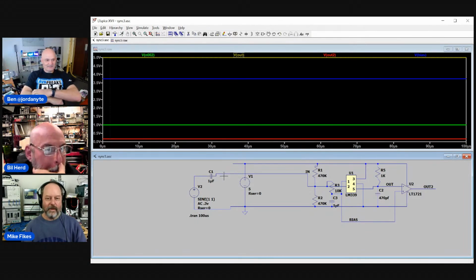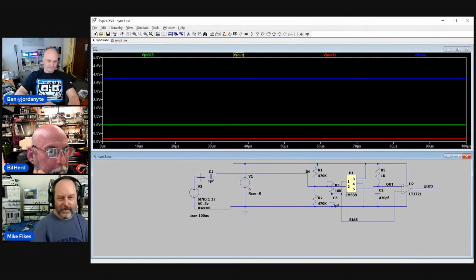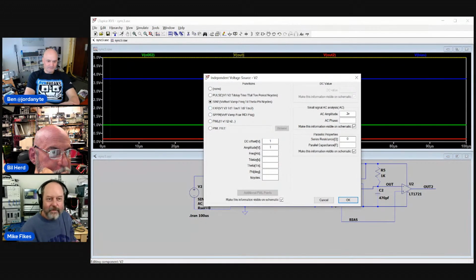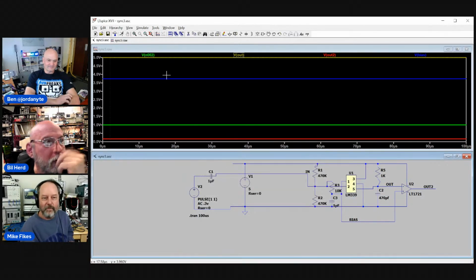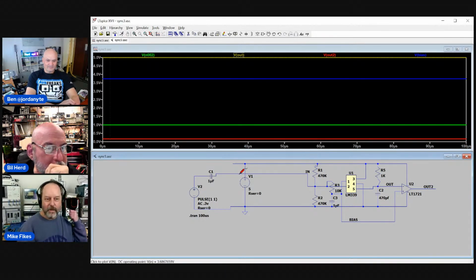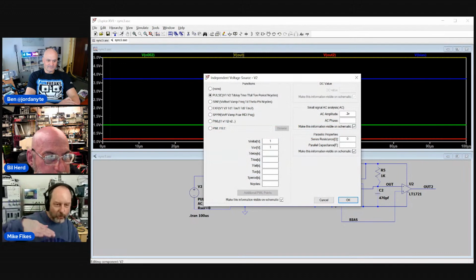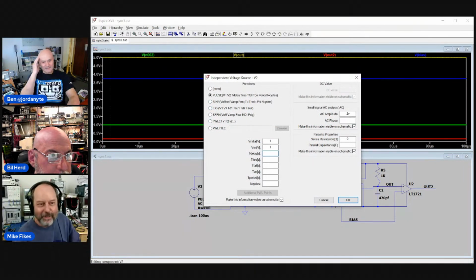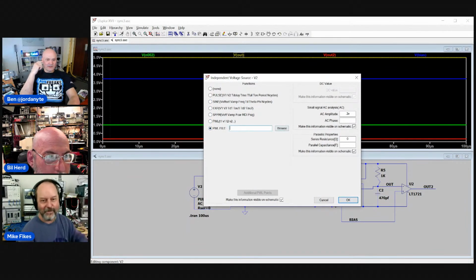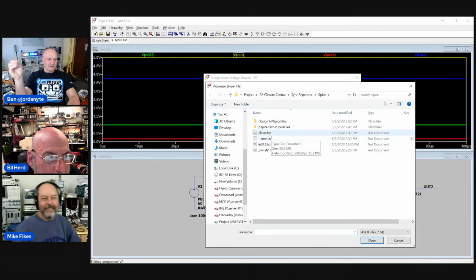One thing I found was I did one of these circuits in Spice, and then I actually went and built the real thing and hooked it up, and I found that it was behaving differently. What I hadn't modeled was the input impedance, or the effect of the input impedance on the source. My little blip that I was generating with my signal generator was being pulled down. In Spice, it was looking perfectly square, so I went in there and changed it and gave it some parasitic whatever. That's right, ESR.